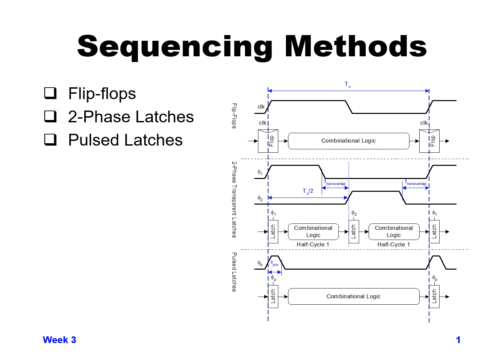And in between the latches we have combinational logic, but each of the combinational logic cones needs to, instead of being a cycle long of delay, be only half a cycle. So we need to break up our combinational logic into half cycle chunks.